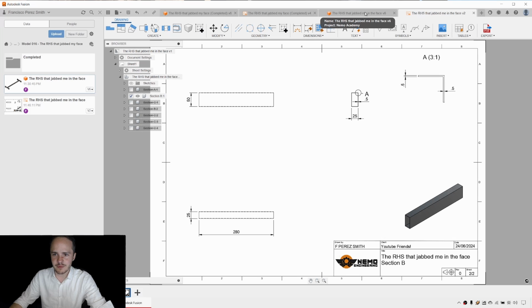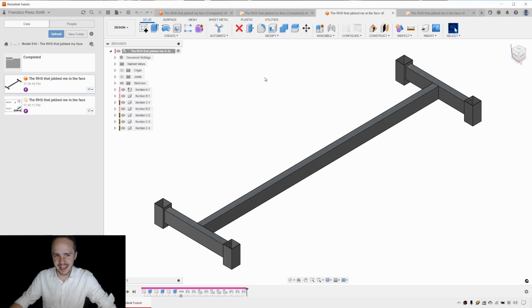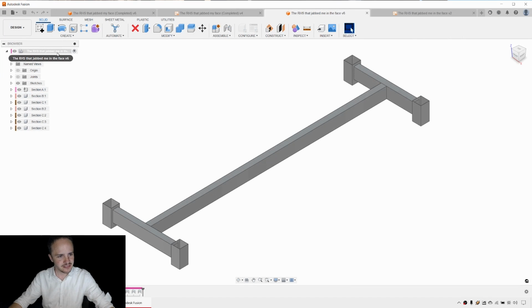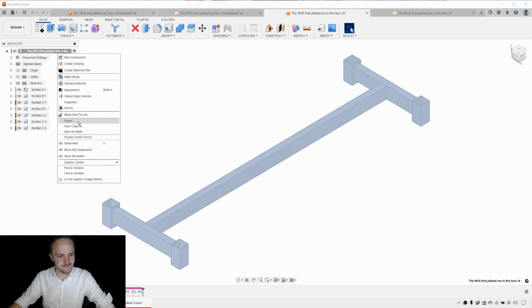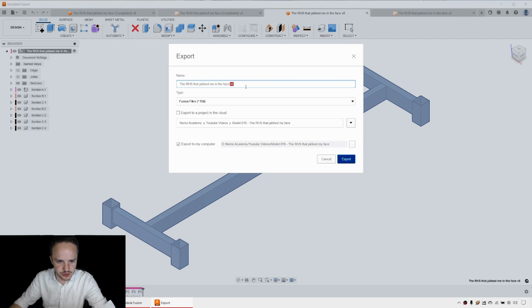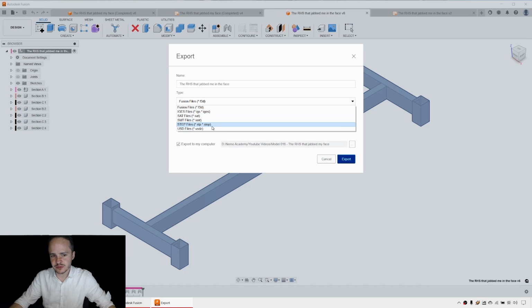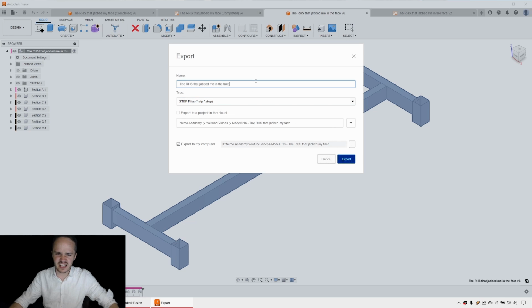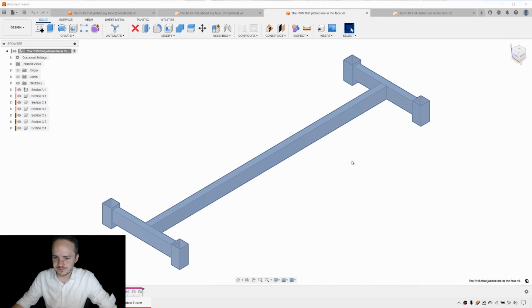And we'll go ahead and we'll come to rectangular hollow section. And here what we're going to do is we're going to export the whole assembly as one big step and then a single component as a step file. So we'll go ahead and we'll choose the entire assembly. So just close the data panel first, choose the entire assembly, click export, and then come along to choose the name. So I just like to delete the version at the end, change the type from Fusion file to step file, choose the location, and I like to add in the revision rev 0 and click export.